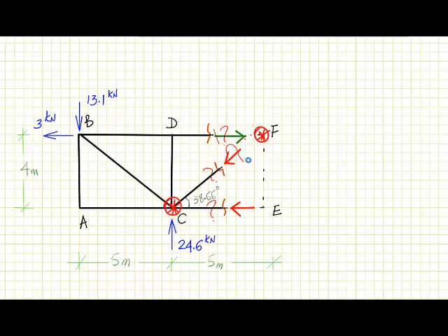For this one, we can use any equilibrium equation, either the sum of all forces in the x direction equal to 0, or the sum of all forces in the y direction equal to 0. I'll explore either one, and we get the values for these three elements by this method. So this is in brief what we intend to do in the method of sections.